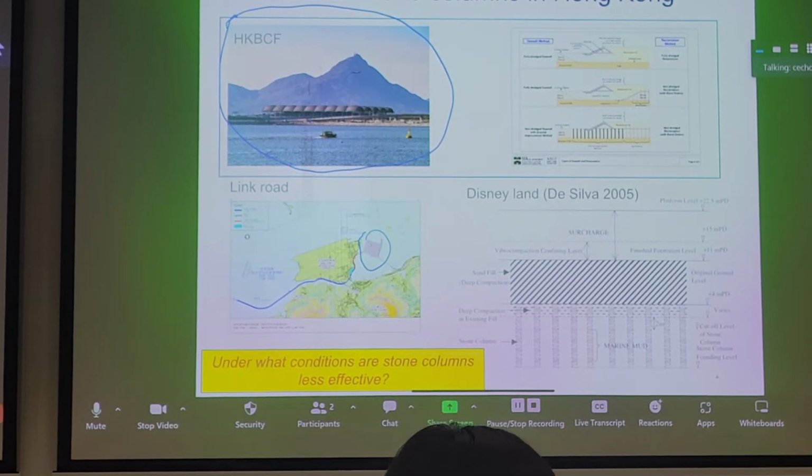The part that was actually the road, the main road to transport machinery, provide access, haul roads, that part was reclaimed using stone columns. And it was rationalized that PVD drains are quite narrow and small, as we saw, but stone columns can have very large diameters, which means they're very pervious.